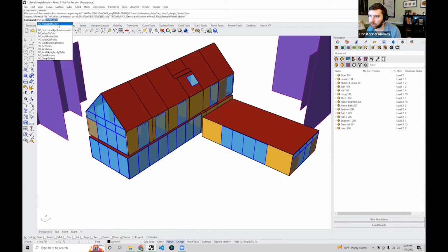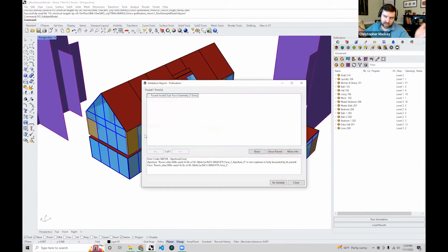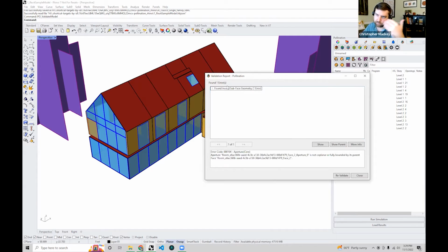If you click this command once you've gotten this Revit model open, it'll ask you if you want to validate just a subsection of the model, if you don't want to validate the entire thing. By default, I'm just going to hit enter and that'll validate the entire model. Of course, that can take a long time for a very large model, but in this case this is only 15 rooms or so. This is pretty quick. And the nice thing is that it basically gives you that same validation report, except that now you can get this in a nice organized list.